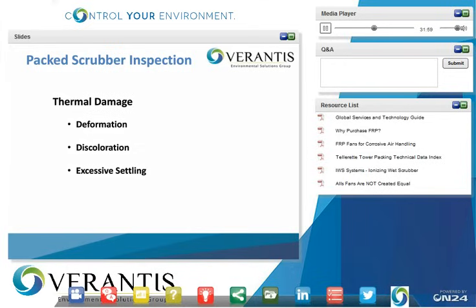Excessive settling is really a result of the deformation we talked about for the first bullet point. As the packing is softened and starts deforming, then the packing bed itself is going to start settling. It's going to basically shrink down. So what happens there is you're going to be decreasing the amount of open area in the packing, which is going to inhibit the flow of gas through the packing and increase the pressure drop.